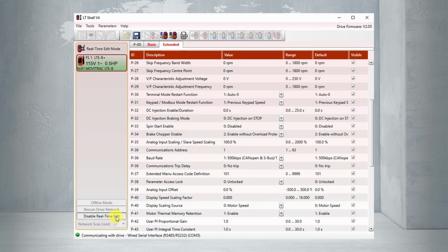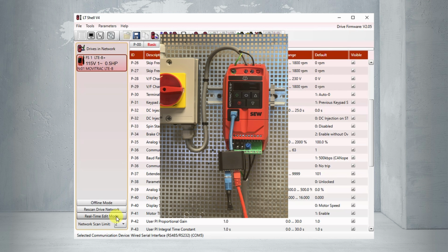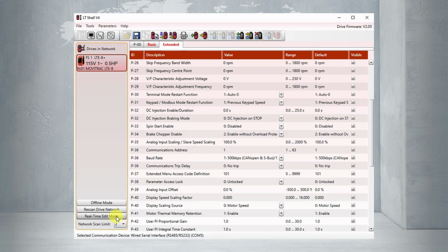What I'm going to do is turn off my VFD and connect up my gateway. You can see this picture. This shows you my setup. You'll notice I've plugged the splitter into the communications port. I've plugged the gateway cable, which is the red one, into one side, and I've plugged the terminating resistor into the other. So I have just one VFD on my network here. Of course, I could connect up to 7 more if I wish, but I won't do that here. Once that's all in place, I'll turn everything back on and we'll be ready to jump into the Ethernet Master Simulator and start communicating.